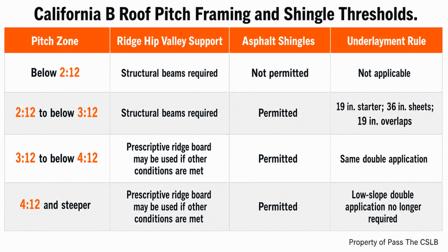surprise. The ridge interface has several prescriptive details worth checking. The ridge board must be at least 1 inch nominal thickness and at least as deep as the cut end of the rafter meeting it. Opposing rafters cannot be offset by more than 1 1/2 inches. They also must be connected with the required collar, tie, ridge strap, or gusset plate arrangement identified by the applicable